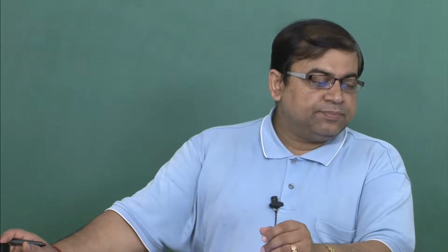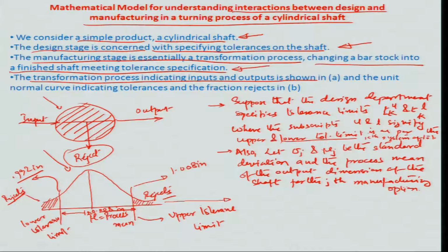So obviously, because there is a theory associated with normal distribution, I'm not getting into it because this is more statistical, you have something called a standard normal variate, okay. And so there will be a variate on the upper tolerance and the lower tolerance, where you're actually measuring the tolerance with respect to the process capability of this particular process, okay.